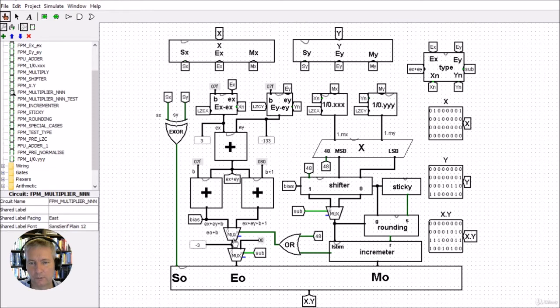And then whenever we get down to the bottom here, you can see that the actual value that we're going to use isn't this value here that we've worked out through this tree. The actual value that we're going to use is just going to be the value 0 because it's a subnormal number. So this little tunnel here overwrites whatever we've done down here, and we just get the value of 0 coming out here. But the reason for still working through this is that we're able to take the values here and use them at the mantissa section here in order to get the right shift. So we can see we're taking the output here and using this in order to get the right shift at the mantissa. So let's have a wee look through the mantissa section.